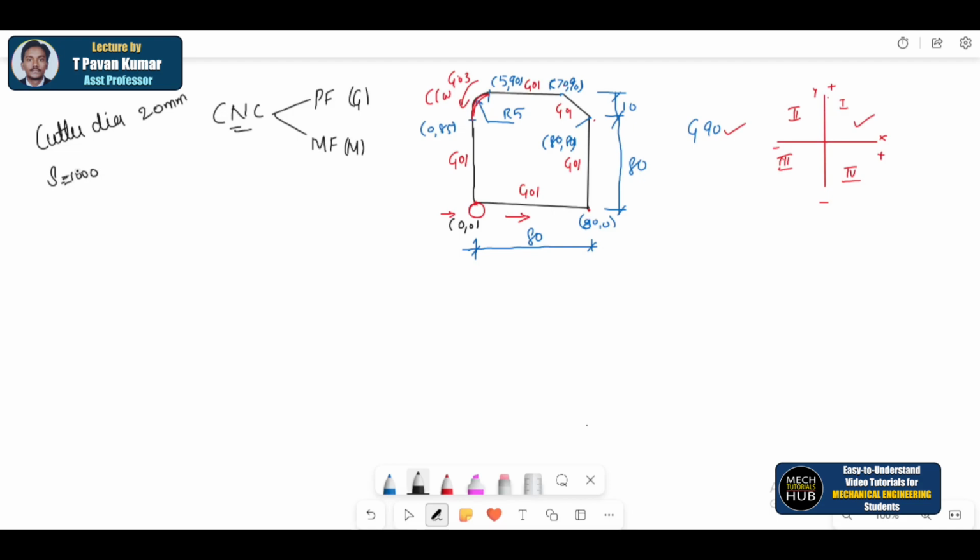For our case, anything is fine, but just for your understanding, f, the feed rate, is equal to 200, and that's it. What else is required? We should know the thickness or depth of cut, which is more important. In some cases, depth of cut is given to you, or else if it is an end milling operation, it is based on the thickness of the plate.